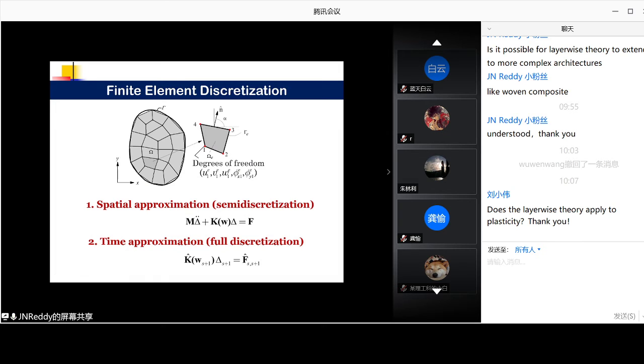They're not at an arbitrary point through thickness. But with the help of the rotation functions, we can find the location of any point through thickness at any time. That's not a problem. That means we can gain 3-dimensional information from plate problems. But most of the time, we don't seek that. We only try to find stress and strains and then use the stress strain information to determine failures.